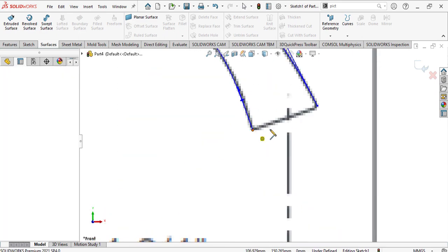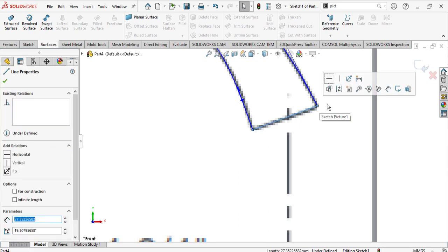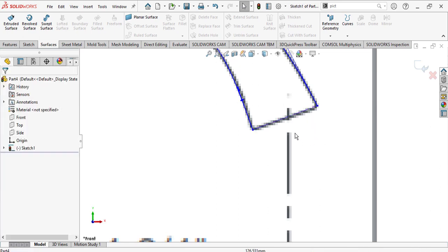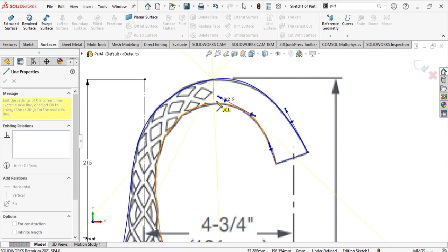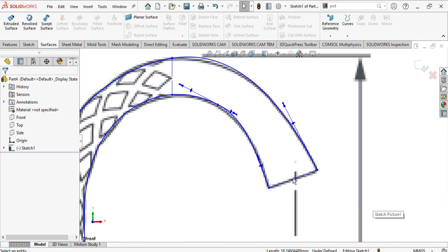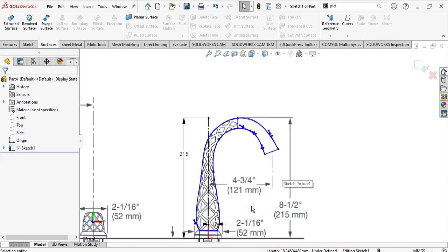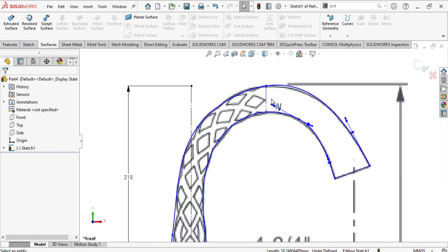Let's make some lines here and make this line concentric. Okay, some lines here also. I will tell you why I made these lines. Actually, I need to ensure I can make a circle profile here. I want to ensure the inside of the main body has many circular openings like this.